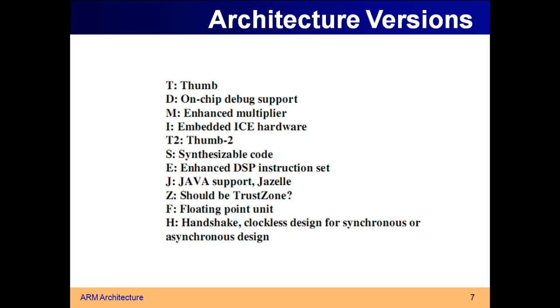But here, in this ARM7 TDMI, in the architecture itself, a particular peripheral known as on-chip debugger support is there. So directly you can connect your microcontroller to a debugging machine, debugging hardware. Otherwise the debugging hardware would be more complicated, but here debugging support is already there.